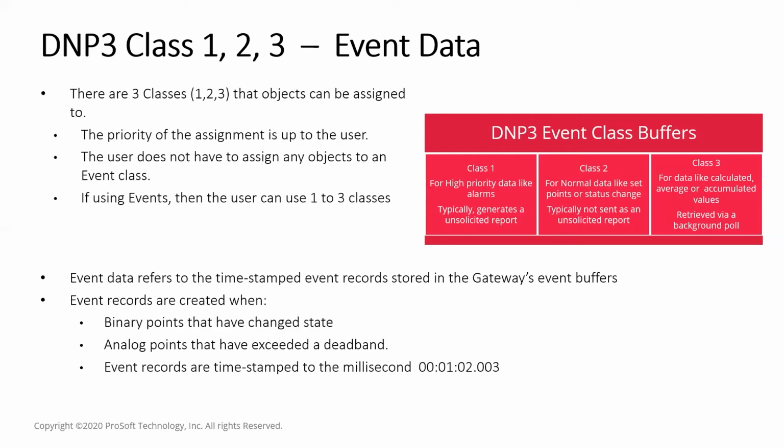So what I mean by that is that typically if you use protocols like Modbus, when you lose communications, you lose data. All you're going to see is like a flat line. With DNP3, because of the timestamping, it records all of that data, and then you can get it back up to the top end. That will allow you to analyze and get a more accurate picture of what happened.